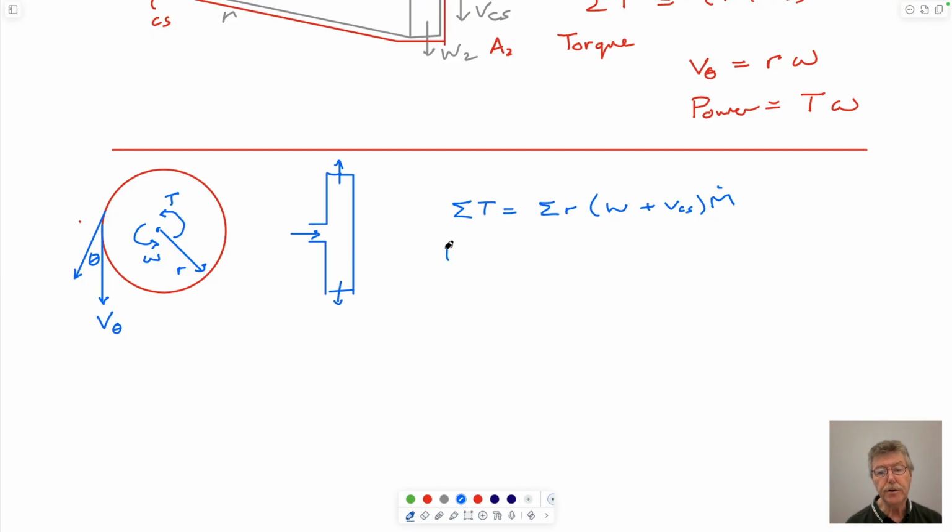So per nozzle, the example that we have has 3 nozzles, coming out like a trident, I guess, but each at 120 degrees. There's 3 nozzles. So if the inflow rate is equal to Q, so this is Q in, each one of these will be Q over 3 because of 3 nozzles.